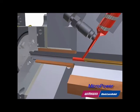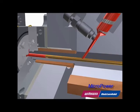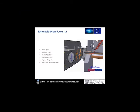So what Wittmann-Bettenfeld have done with their machine design is we still have a fixed screw here, but basically we've done away with the checkring. So we no longer have that checkring there, which is causing this problem with this unknown amount of material that could be conveyed in that checkring. So this screw still moves backwards and forwards to dispense material, but by not having this checkring in here, we're able to deposit slightly more accurately.